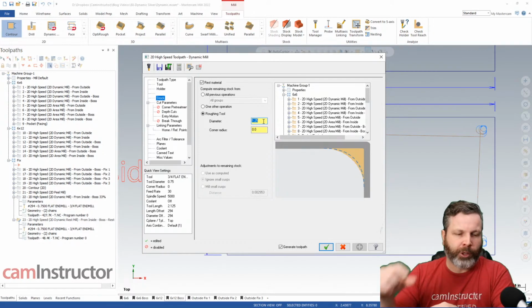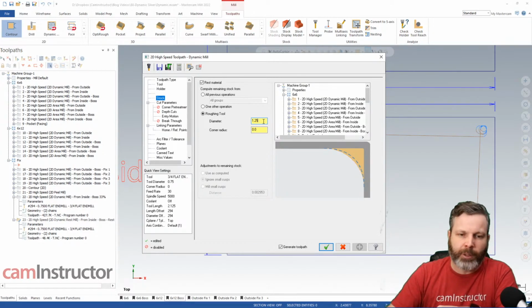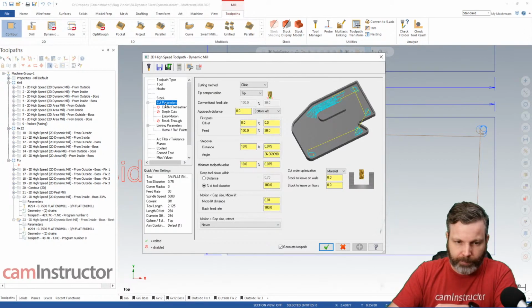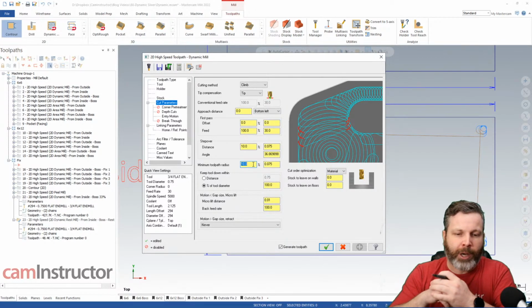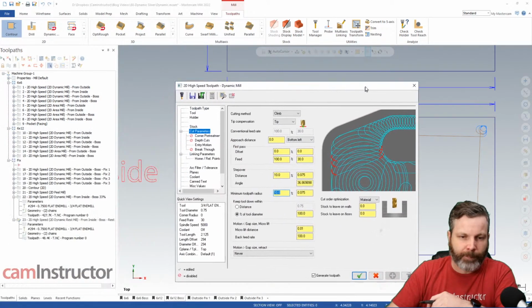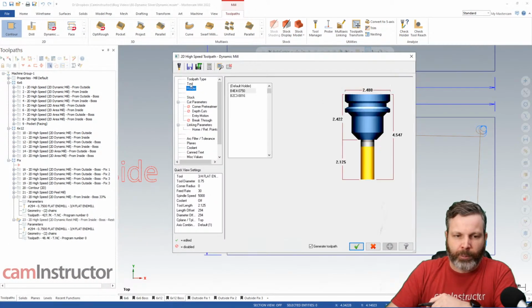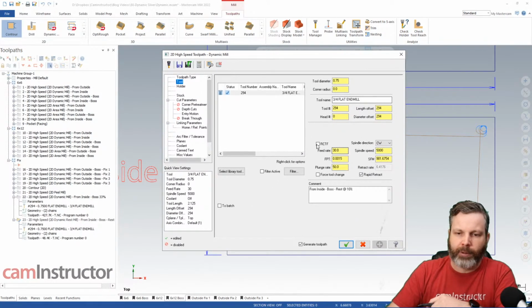So basically, with a quarter inch radius, I took the 3/4 inch cutter, added the radius to it twice, gives me a roughing tool diameter of 1 1/4 inches. And on this one, I've set that minimum toolpath radius back down to fit so that it does fit up into here. Okay. So this will make tool motion only in the uncut sections at the reduced feed rate.